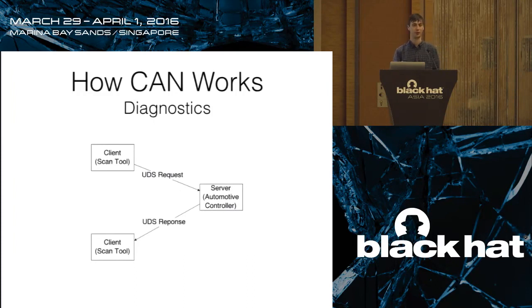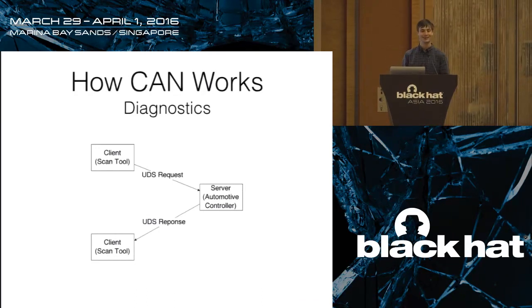So they came up with this OBD, which is really a read-only protocol. The only thing you can really write with OBD is you can clear fault codes, but you can read out what are called PIDs or parameter IDs for all sorts of stuff. You can get vehicle speed, engine RPM, airflow values. You can get temperature sensing, all kinds of information. It's all standardized. There's a great Wikipedia article that has every PID. It's basically the number one reference online for that information. But OBD, that's the limit. You can get fault codes, clear fault codes, that's it.